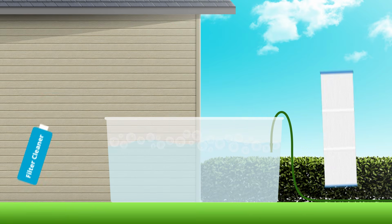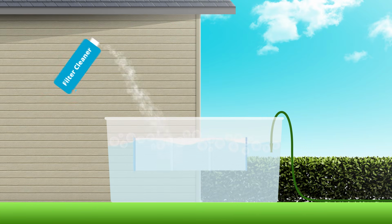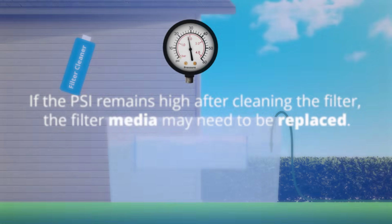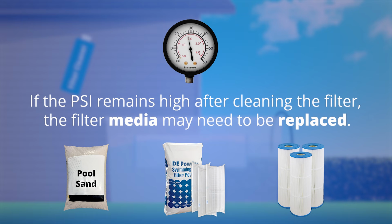DE grids and cartridges can also be soaked in a filter cleaner to remove oils and grease that aren't removed during normal cleaning. If the PSI remains high and you still have low water pressure after cleaning the filter, the media may need to be replaced, and by media we mean the sand, DE grids, and cartridges.